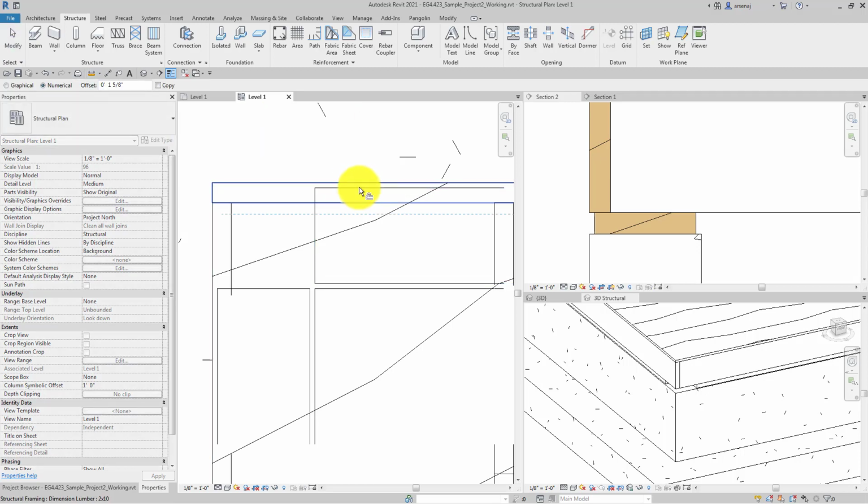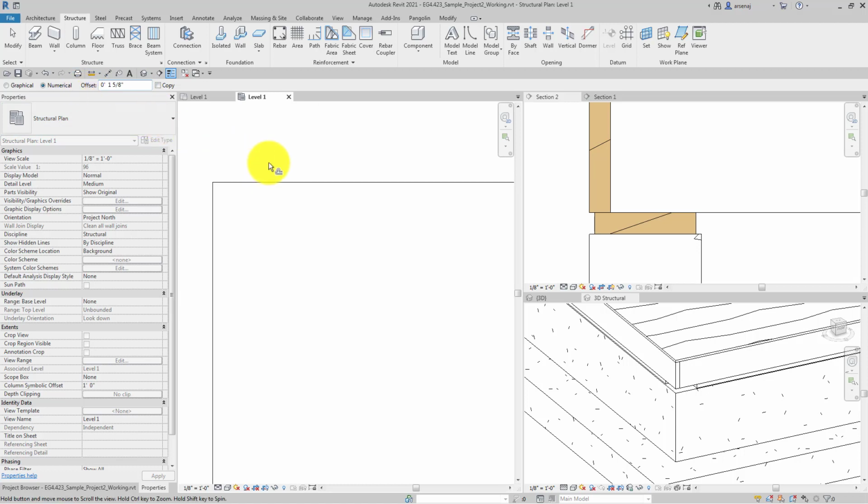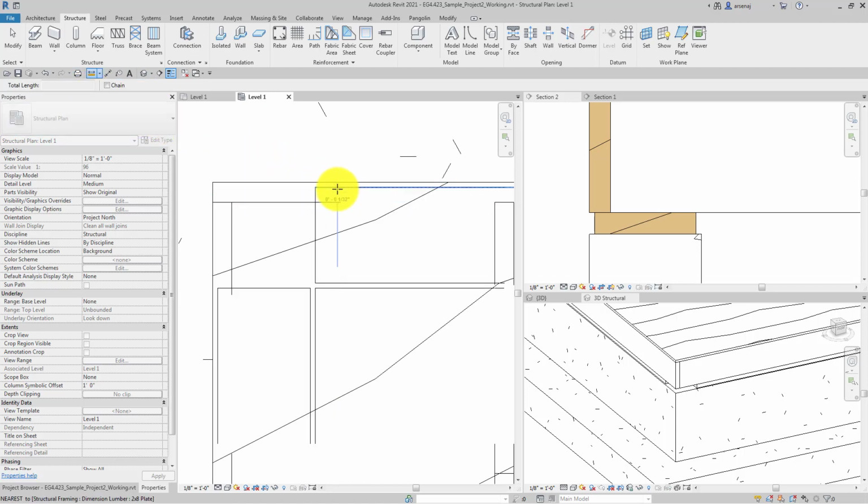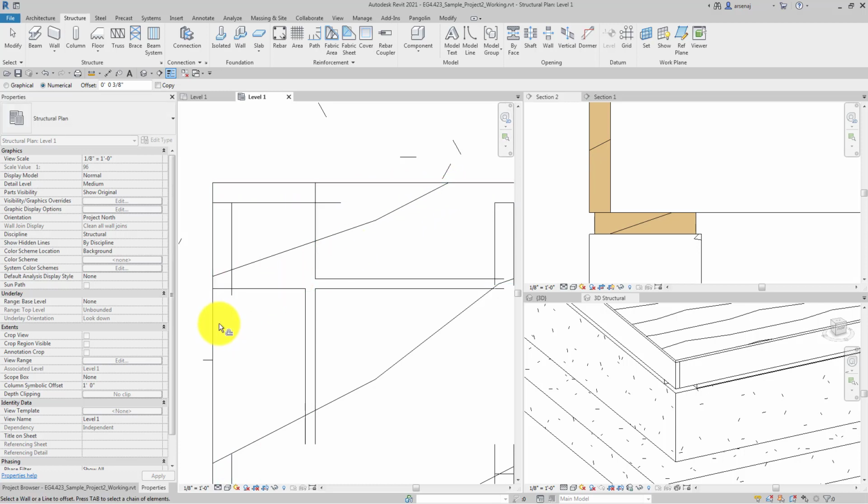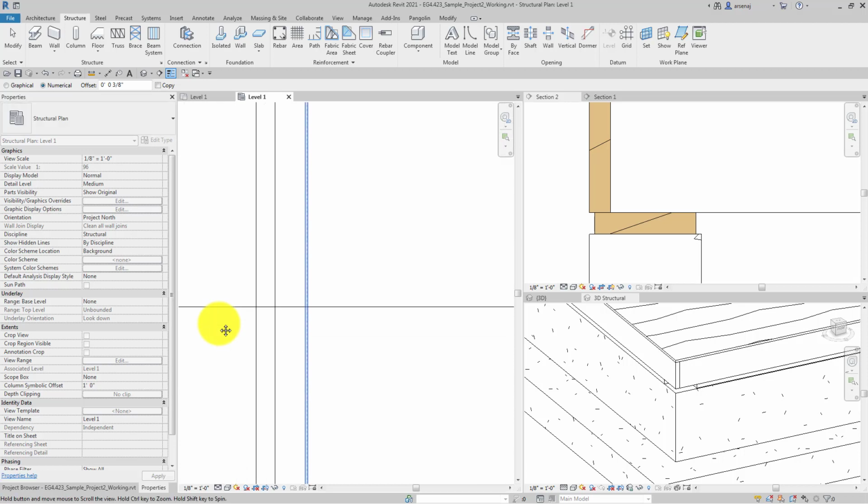Let's offset this 2x8 plate. As you can see in this drawing, you can take a measurement. It looks like it's 3/8 inch from there, so that's the offset, and we'll do 3/8. We possibly are not going to be able to get all of them at once, so we may have to go through and pick each one, and then we'll fix up these corners.